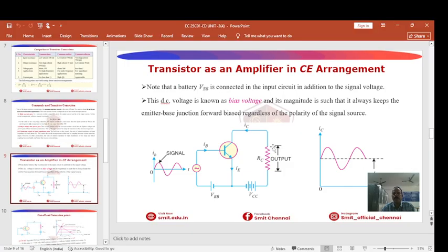You see here how a transistor can act as an amplifier in the CE mode. The input signal is applied, you measure the amplitude, and you see the output that is taken from the collector resistance, on the output side of the CE configuration. You see the enlarged sine wave. This indicates the nature of amplification done by means of CE mode, because it has a very good voltage gain. That's why it gives a faithful amplification of the signal.